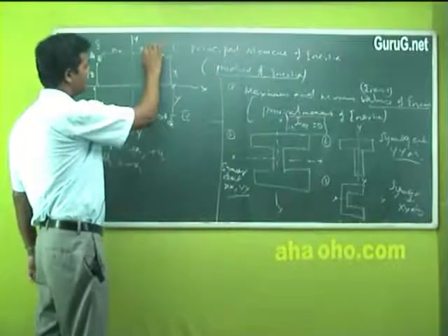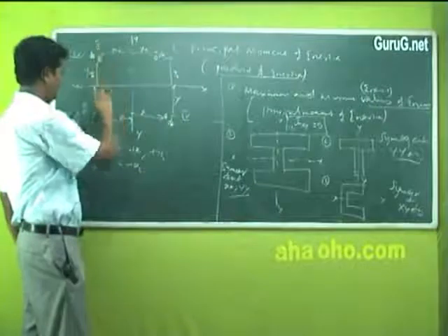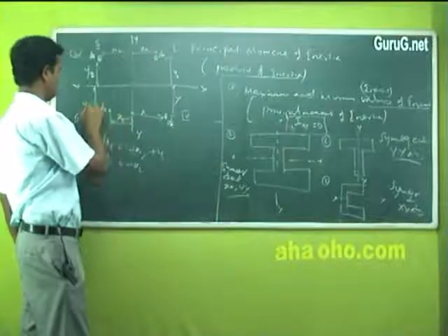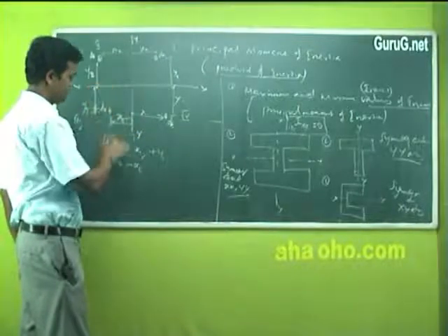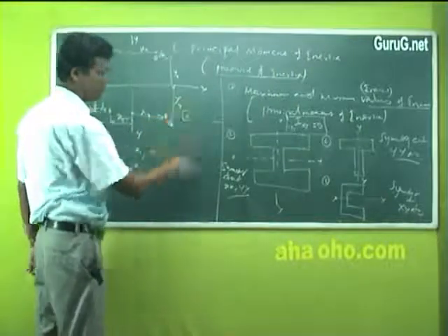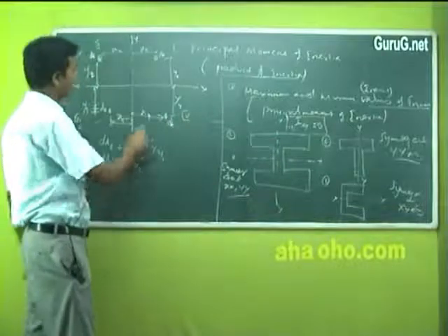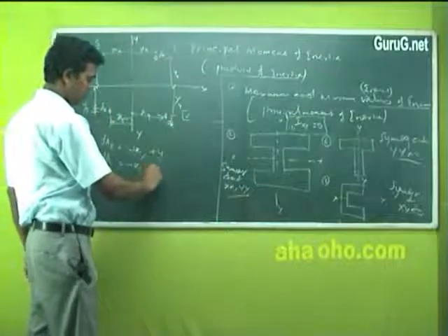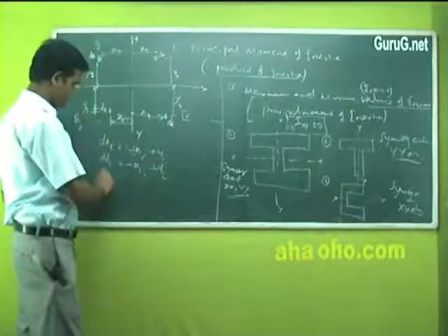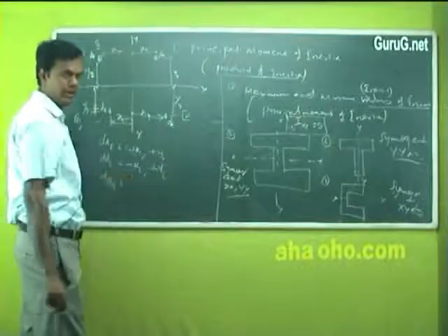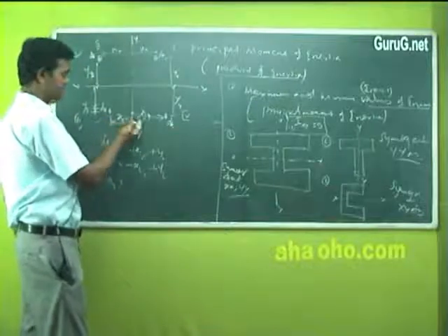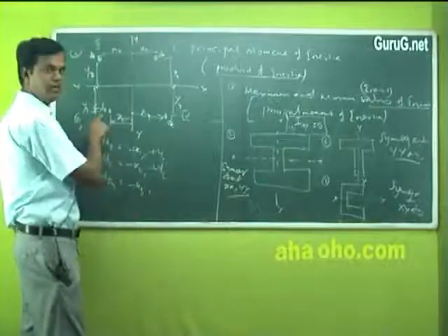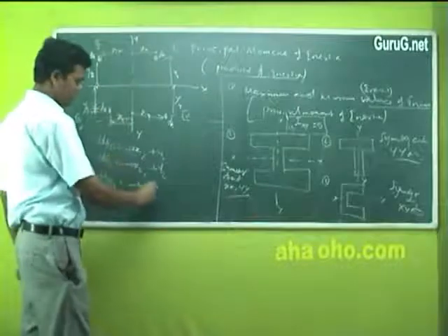So to avoid confusion, x1, y1, x2, y2, x3 distance and y3 distance, and x4 and y4 distance. So dA2 is minus x2 because left to y axis is x2. What about y2? y2 is above, so it's positive, comma plus y2. For dA3, coordinates I'm writing, what about 3 here? x value is left of y axis, so it's negative x3, comma, what about y value? y is also below x axis, so negative y3.